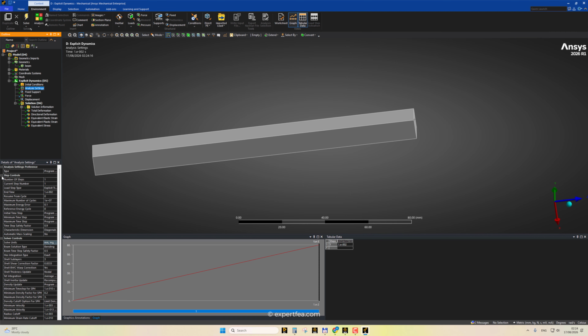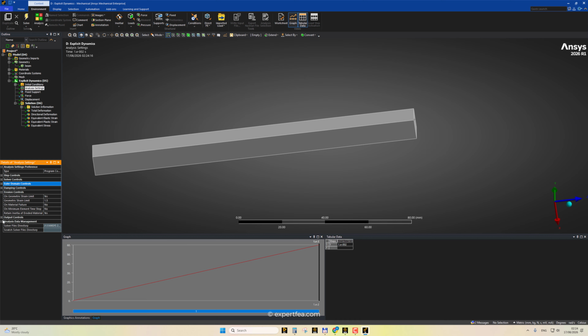But because we are here, we'll do our best to make it work and fracture occur. So our option is this one. The software by default lets the part, the mesh, whatever, stretch 150%. 150% over 100, yeah, is 1.5. This is too much, let's say.